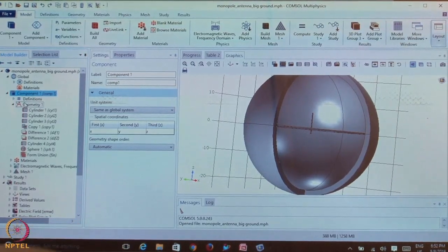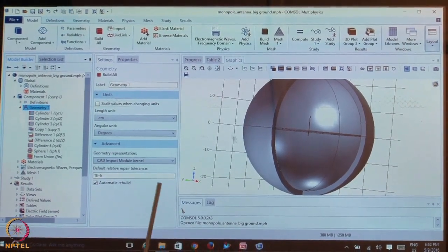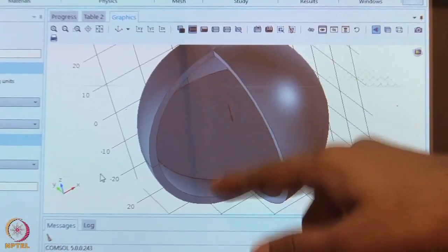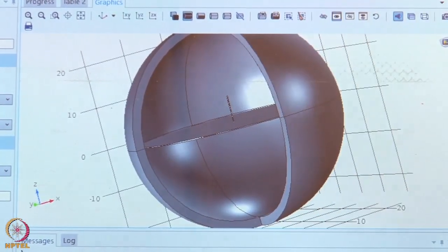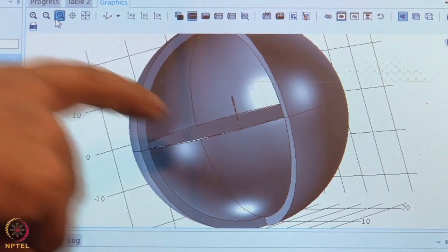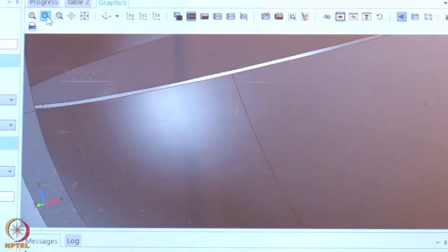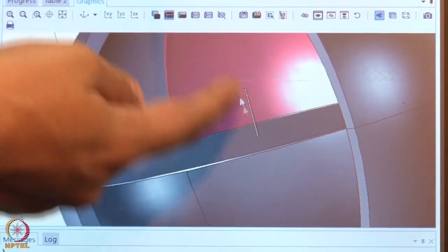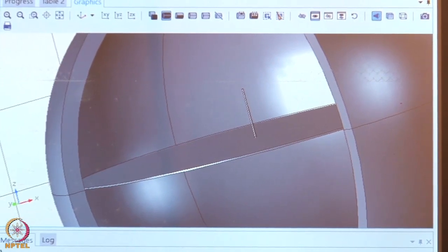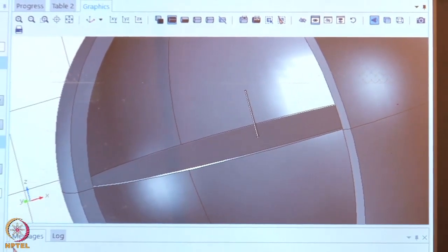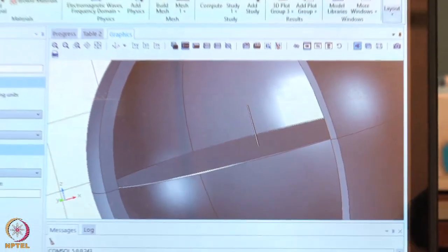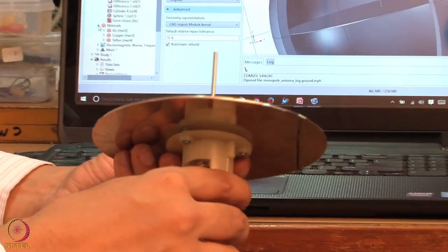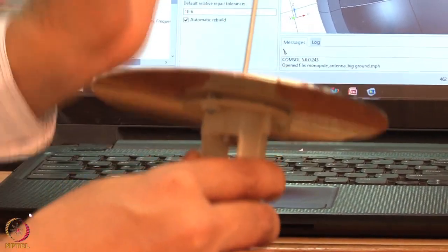So you're basically modeling this particular geometry using the finite element solver. The domain is entirely enclosed with this PML, perfectly matched layer. I have hidden it just to show you the inside part. So what you have here is the domain and its internal geometry. What we see here is a reflector plane, and you have a lambda by 4 monopole. Practically, to compensate for the inherent capacitance in the design, we reduce the length slightly. It's not exactly lambda by 4; the length is reduced to a bit less than lambda by 4.